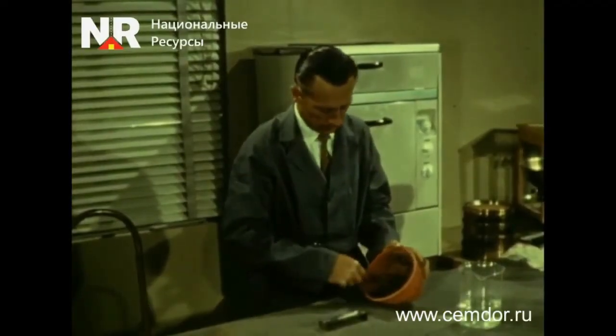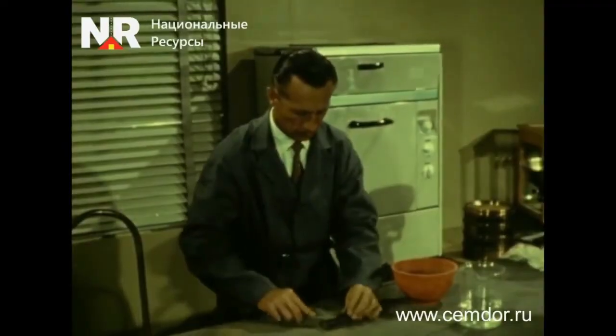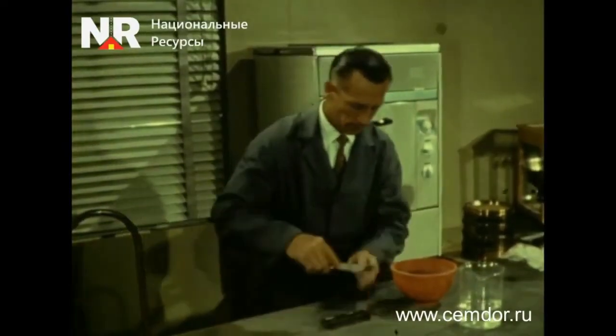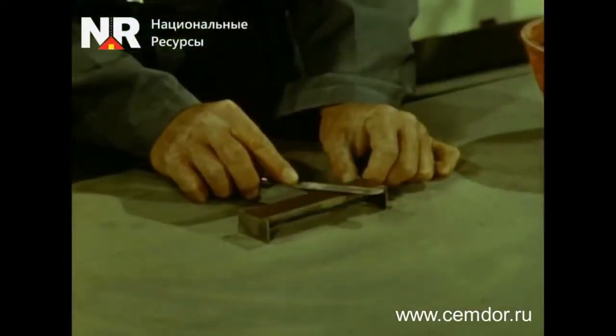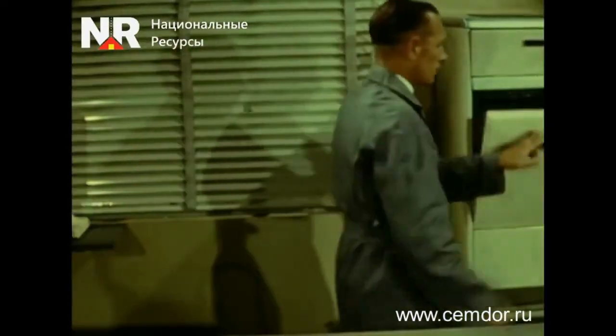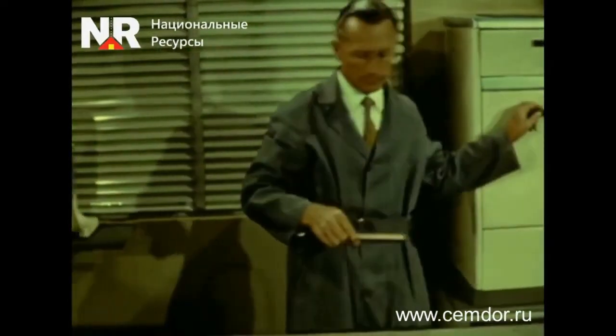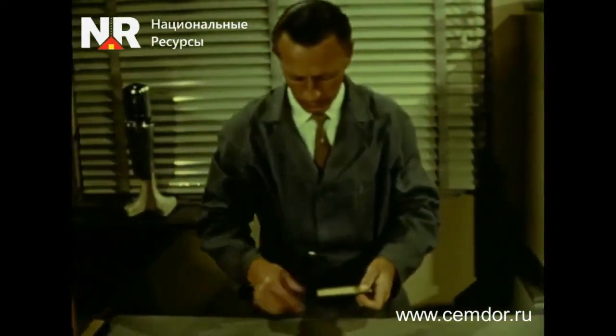Linear shrinkage is the third characteristic of soil. Soil shrinkage refers to its ability to decrease in volume as moisture evaporates from it. The soil is mixed with a certain amount of water, and the resulting mixture is placed into a special mold. Then the soil is dried to a constant mass, and the amount of shrinkage is determined.